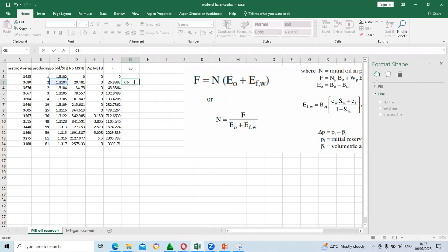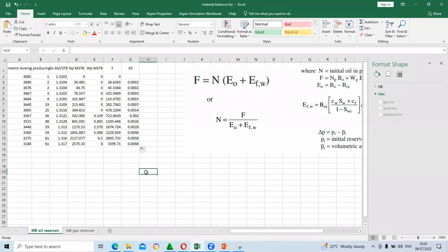Because if you don't put that value, once you drag it down, you will be taking this one, subtracting it from the previous, which is wrong. The right calculation is you have to subtract it from the one that was there at the beginning. That's where you know the real value minus that. So I'm going to put it as a constant. All right, so I drag it down now. It does a calculation for me.